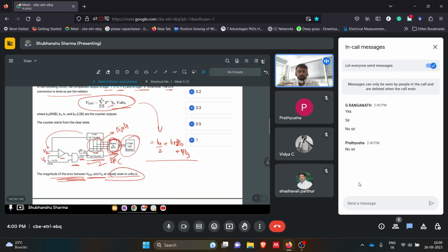That is the first point from where we start thinking. The first thing in our mind should be to make this 4-bit counter stop, because only then will there be a steady state for this LED display. And how will it get stopped? It will get stopped if this clock signal becomes zero.